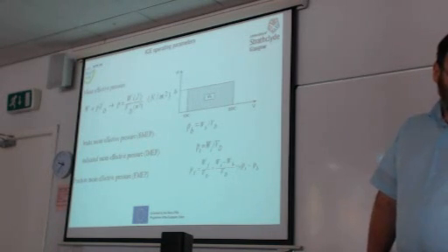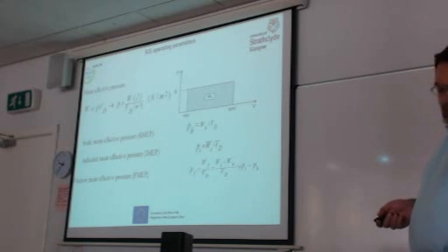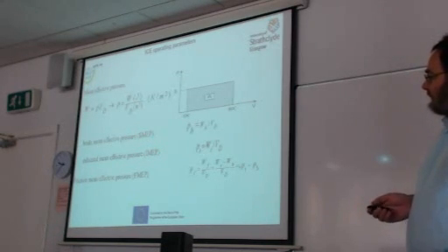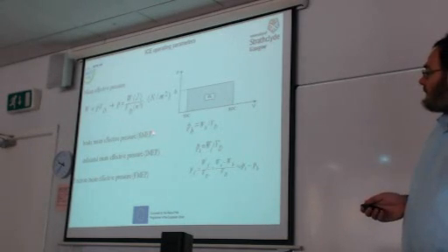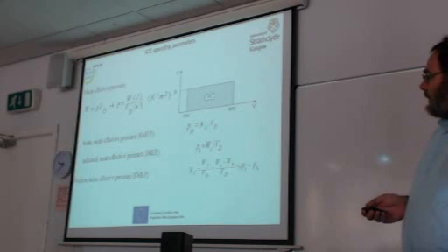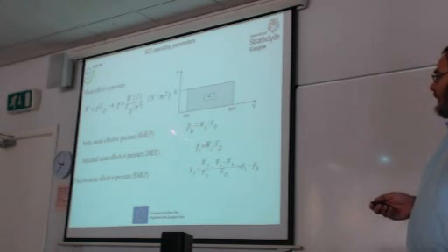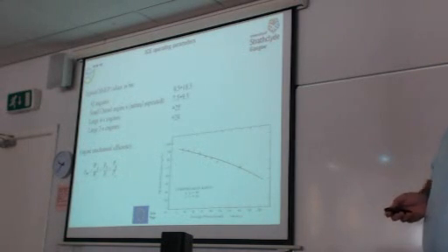I will pass some slides providing information about the main operating parameters of internal combustion engines, because we will see these parameters in later slides. So BMEP, brake mean effective pressure, is an important parameter used almost universally for characterizing engines, and by definition it is the brake work divided by the displacement volume. Of course, we can define respective indicated mean effective pressure and friction mean effective pressure, but usually brake mean effective pressure is used.